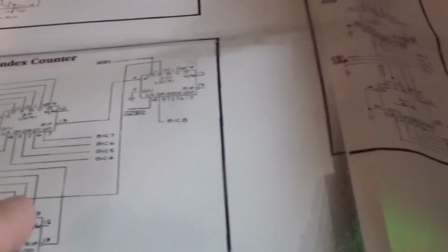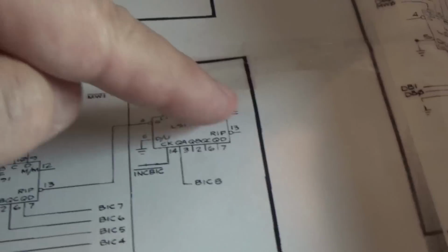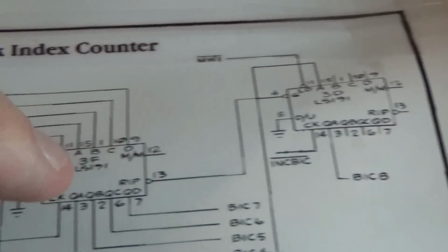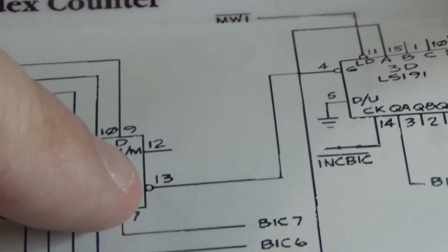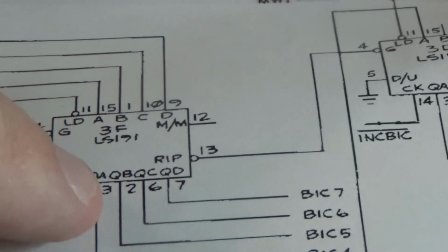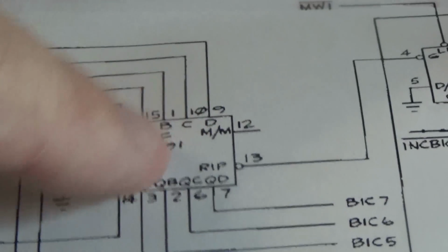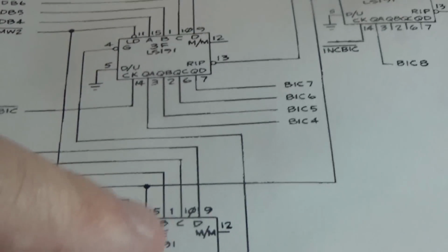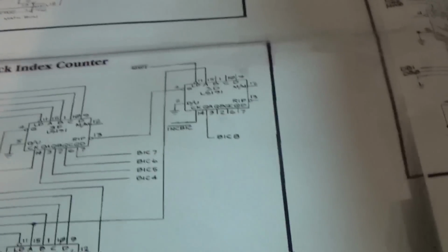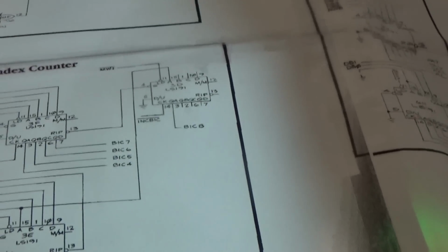What I was finding when I was looking at these guys is this one was never being activated, ever. This ripple would never go low, meaning this was not terminating. I put the analyzer on all of these 191s, and over here there's a couple more, and I didn't see anything to where they didn't work. They were doing what they were supposed to do.